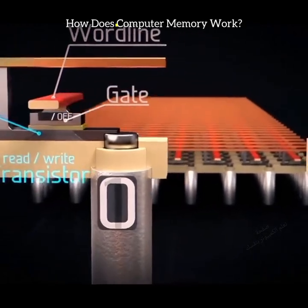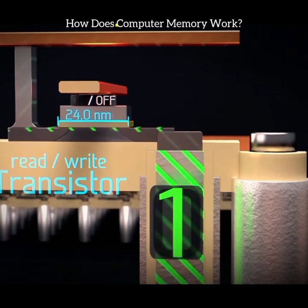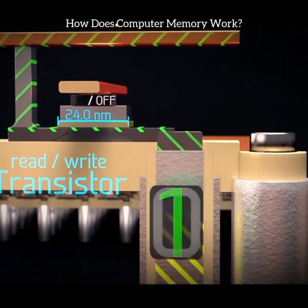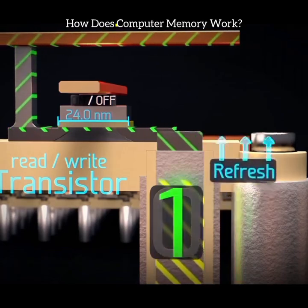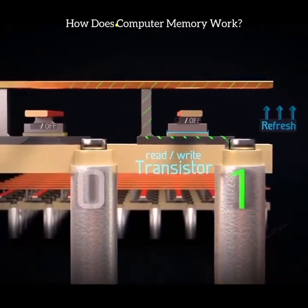Note that because this transistor is incredibly small, only a few dozen nanometers wide, electrons slowly leak across the channel, and thus, over time, the capacitor needs to be refreshed to recharge the leaked electrons. We'll cover exactly how refreshing memory cells works a little later.